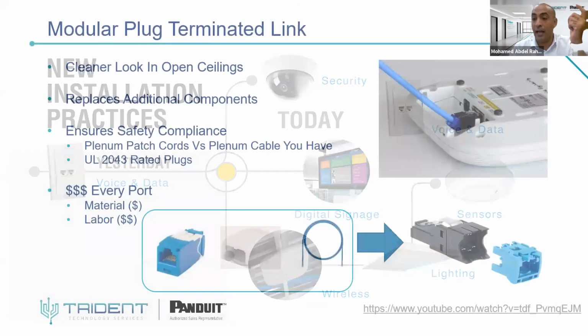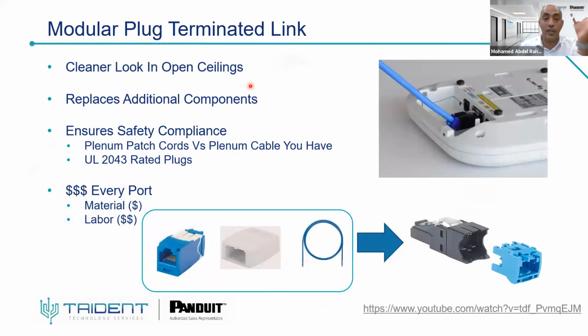So Panduit has an innovative solution. It's called a field terminated plug, or by the standard, approved by TIA in 2018, it's called MBTL, modular block terminated link. This cable module can be used for direct connections to devices like wireless access points, LED lighting, or even security cameras and sensors. You can use this modular block terminated link for any device, even one you have not planned for, if it changes location. So it is very simple.